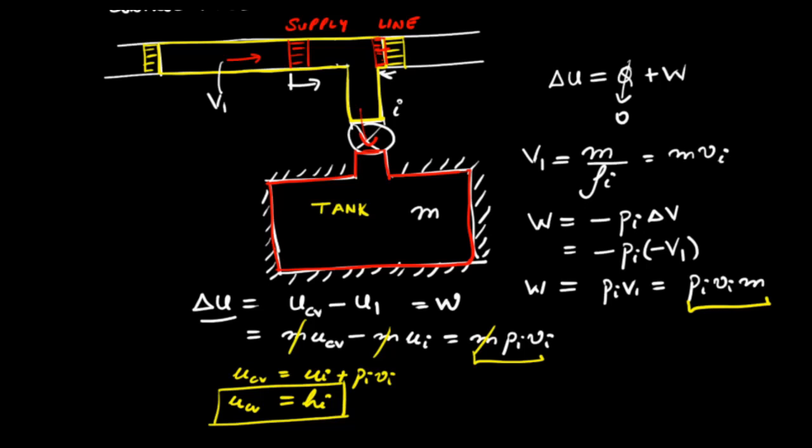So this example again shows that applying the first law to a control mass or a control volume would result in the same conclusion. Only the mathematical formulation of the principle of conservation of energy is different for a control mass or a control volume, but the final result would be the same. You can use either the control mass or the control volume approach to analyze the same problem, but for cases where we have mass transfer to the system, it is more convenient to use the control volume approach.